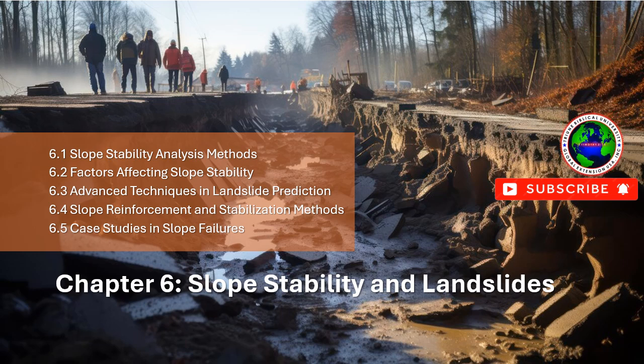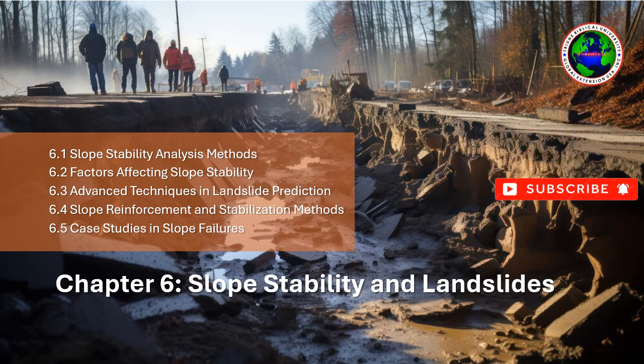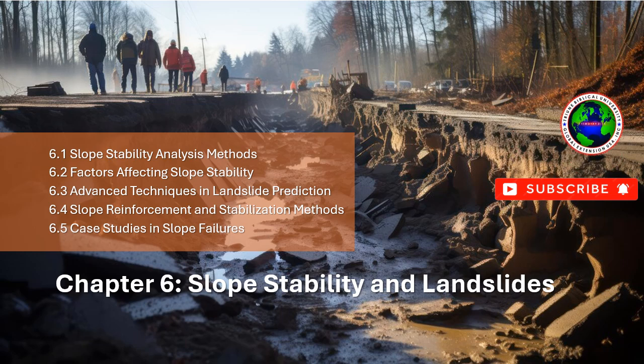Pore pressure and fluid flow modeling. Simulating the movement of water through soil layers is a critical component of landslide prediction. Numerical models that include pore water pressure, groundwater flow, and drainage conditions can predict how changes in water content affect slope stability.